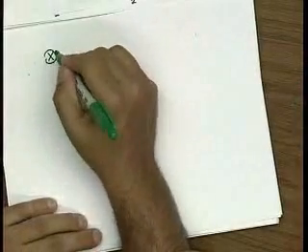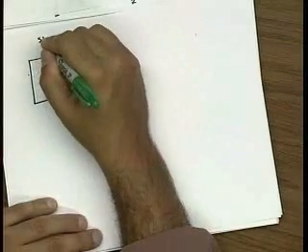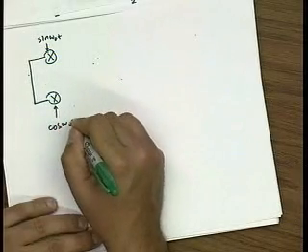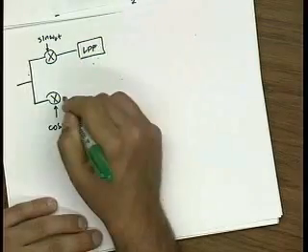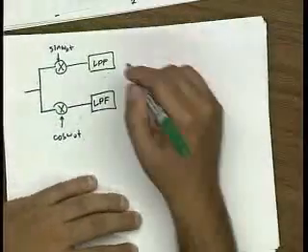So what I'm going to do now is try to show you how this image rejection scheme works based on what we've learned so far. Okay. So first of all, I'm going to put in low-pass filters to get rid of the up conversion. I'm just going to focus on the down conversion.